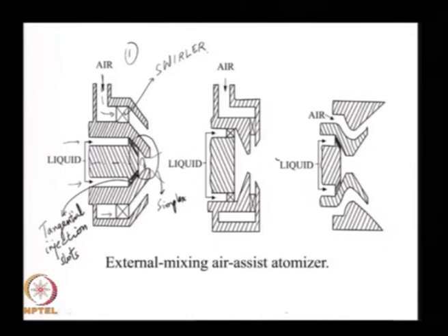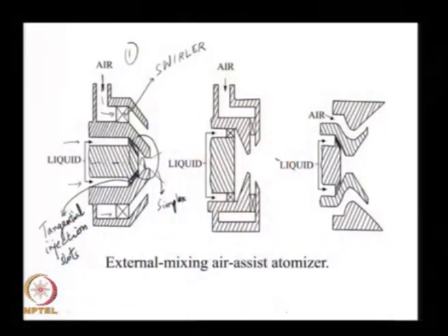Typically, a swirler is used to decrease axial momentum flux, and you do not want to dissipate momentum. So, essentially it is there to decrease the axial momentum flux and increase the swirl momentum flux. Okay. So, this air swirler causes the air coming out of these passages to take on a swirling velocity field and is now allowed to directly impact this spilling film.